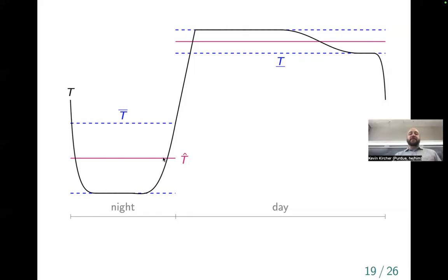Yeah, so that's very perceptive. So here there actually would be a weird step change in X. If we plotted X, there would be a jump in the graph, because we go from having T hat, the nominal thing, at say 68, all the way to T hat at 72 instantaneously. So here, at the end of this, we're at just about 0 energy stored in the definition that I gave. And then bang, suddenly the set point jumps, and now you're at, I don't know, negative something, negative 10 kilowatt hours or something like that. So it's like someone just extracted a bunch of energy from your battery, and then you have to work really hard to basically fill it back up. Does it make sense?